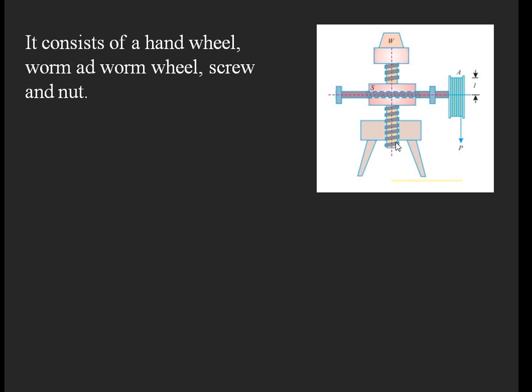Okay, basically in the actual instrument the nut will be placed in the worm gear only. So when you are mounting the worm gear, that worm gear will be mounted in a nut. So into that nut the main screw will be inserted. So through that nut the main screw will be moving up and down according to the rotation of the worm wheel.